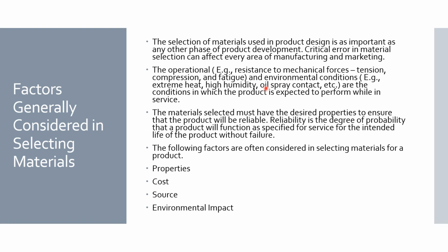So for operational conditions, we take a look at the tension, the compression, the fatigue, all these mechanical forces. And you have to choose the right material to satisfy all of that in your design. And then for environmental conditions, we take a look at the heat, humidity, and the oil spray contact, everything that can affect the environment in which your product is going to be used. We consider all of that. If you don't consider it, you're going to have an issue choosing the appropriate industrial material to make that